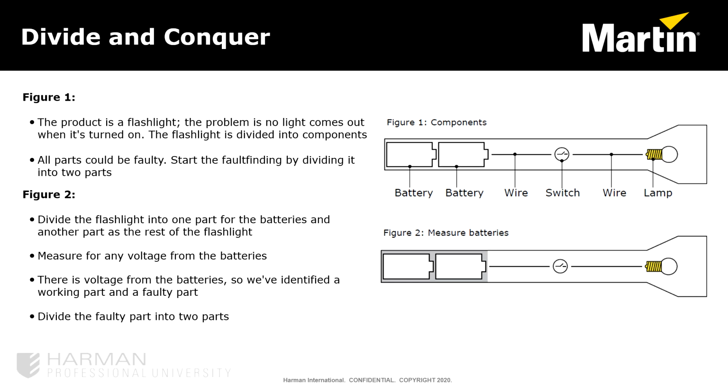To find a fault with a fixture, it's best to start halfway. Take a measurement from the input of the igniter to determine if the ballast is providing enough power for the igniter. Do not measure the output of the igniter. On many fixtures, you may not be able to access the igniter to measure from the input. So in this case, it is best to measure the output of the ballast directly from the ballast.